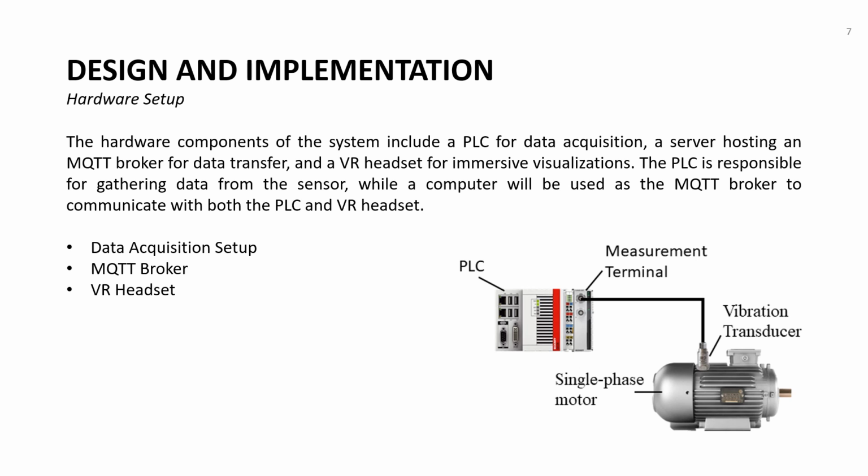So the system consists of two main components, the controller and the sensor, as seen in the figure. The PSC utilized is a Specov CX5130 embedded PC, which has an Intel Atom processor and 4GB DDR3 RAM, and it's running Windows 10. The PSC is of course powered by a 24 volt power supply, and it also has an ELM3602 IEPE measurement terminal, which has a max sampling rate of 50,000 samples per second.